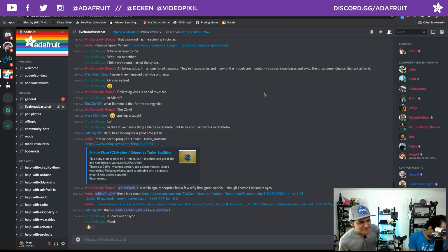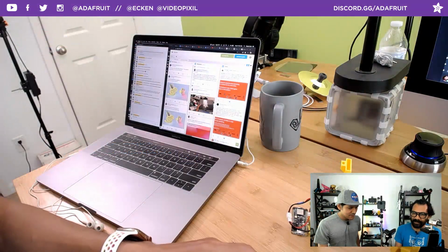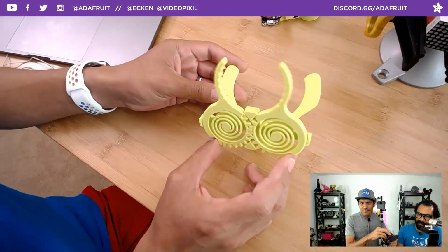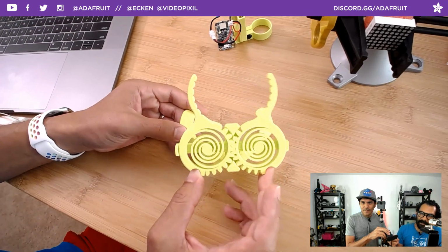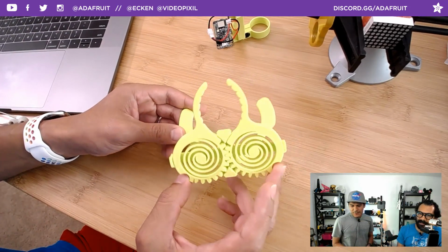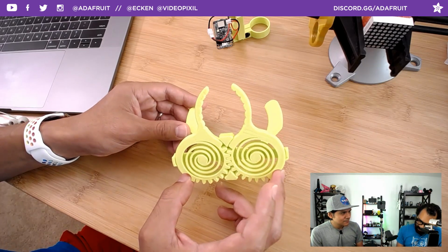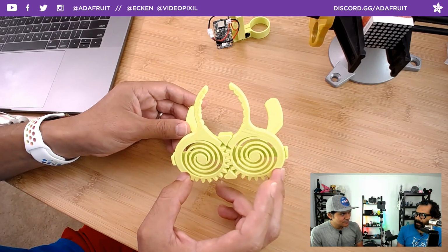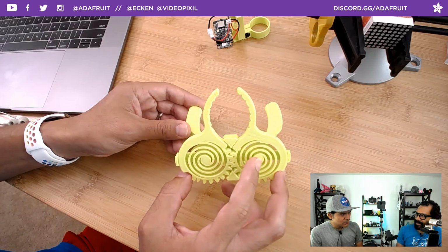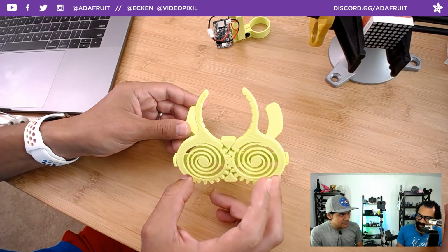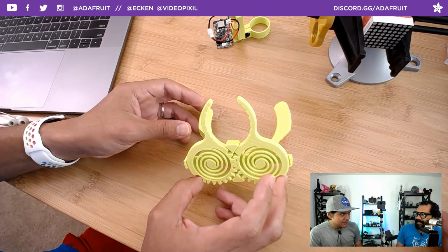I think one of the recent questions on the YouTube comments was whether I can make follow-up videos for this week's Time-Lapse Tuesday. There was a lot of stringing going on, and they asked, "What temperatures did you adjust? Was it retraction?" How did I fix this up? I had to get a new Bowden tube, a new Z probe, and the nozzle on it. Some wiring needed to be redone.